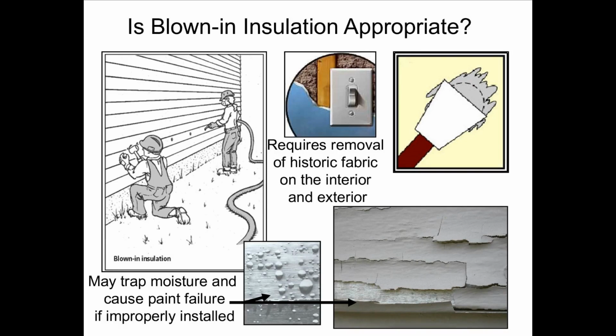Is blown-in insulation appropriate? Not necessarily, because it requires removal of historic fabric on the interior and exterior, and it may trap moisture and cause paint failure if improperly installed.